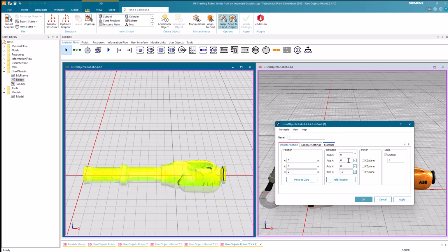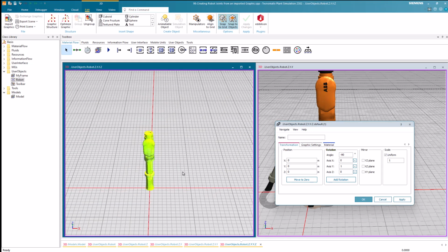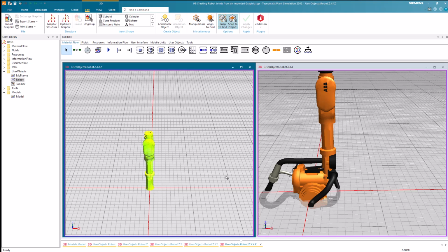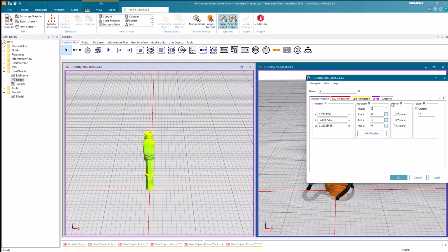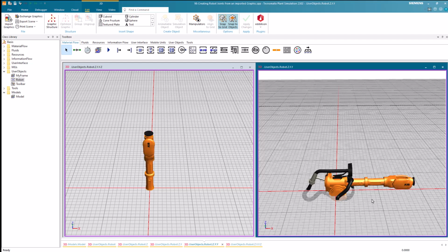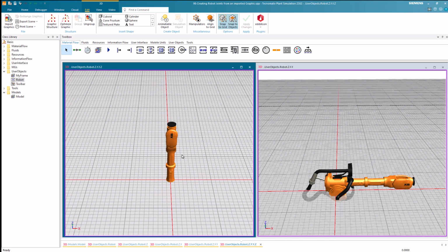Now we can easily rotate the joint around the y-axis by -90 degrees. However, it is now necessary to navigate back to the previous joint. At this point, we need to rotate the joint once again around the y-axis by 90 degrees. By following these steps, we have successfully adjusted the configuration such that they align with the supported configurations. To continue with the next joints, we need to ungroup the joint again. For the sake of time, let's skip to the last joint.